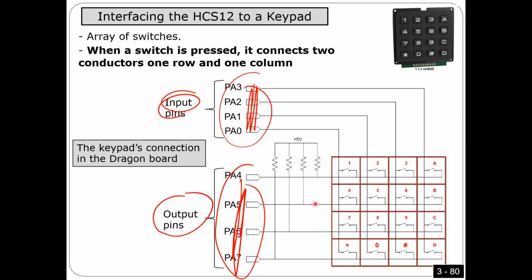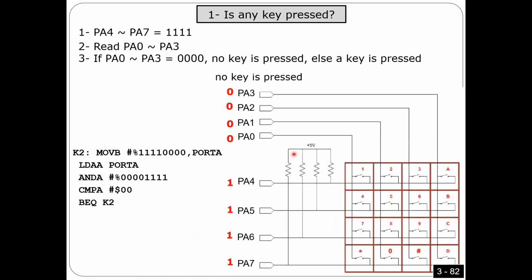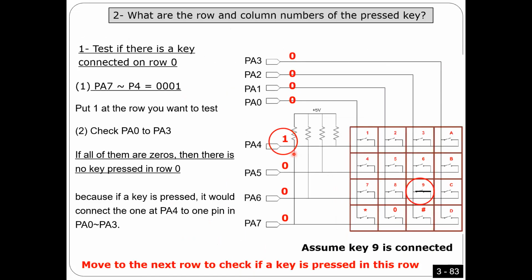So you have wires here, 4 rows and 4 columns, as you see here, guys, and they are not connected. However, at every intersection, we put a switch, like a button like this one. Every button is at an intersection, right? But again, there is no electrical connection here. The idea is that when you press a button, you actually create a short circuit between one row and one column. Now I have to write a code to see where this short circuit is.